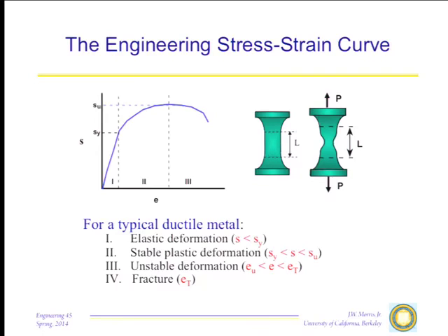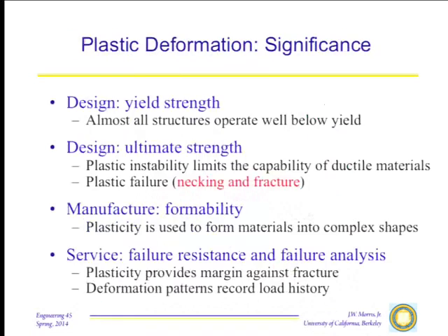So very often in structures and engineering devices, part of the specification of the steel that's used to construct them is the strength ratio, the ultimate to yield, which measures the cushion you have against some kind of overload event on the material. So those are all important.